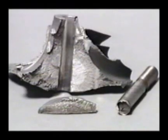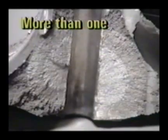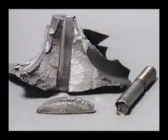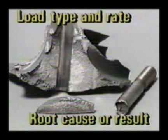While attempting to identify fractures, keep in mind that more than one fracture type is usually present on a fractured surface, and fractures often do not contain all of the identifying features every time. Nevertheless, by applying the rules you learn in this lesson, you will be able to correctly identify fractures. Once you correctly identify a fracture, you can determine which load type and rate produced it, and whether or not the fracture was closely associated with the root cause of failure.